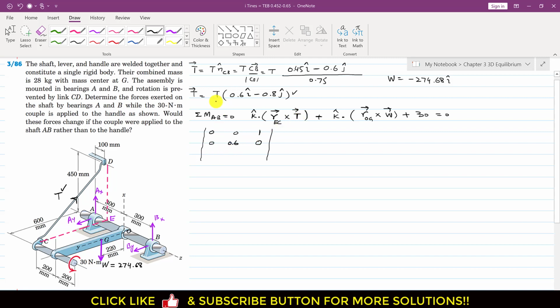And now we will write this T. So I will write the magnitude T outside, and this is 0.6 i and minus 0.8 j, and this is 0. Similarly, I will write plus, and again the k vector is 0, 0, 1. ROG. So again, to reach that point G from O, we need to travel 220 mm distance, or 0.22 meters, right, in the positive y direction. So I will write plus 0.22, and the i component is 0 and the k component is 0.